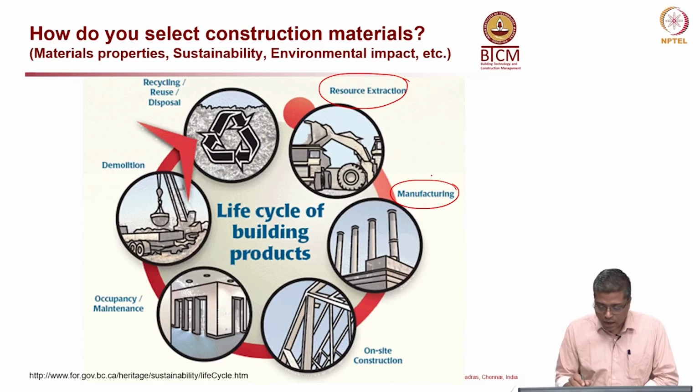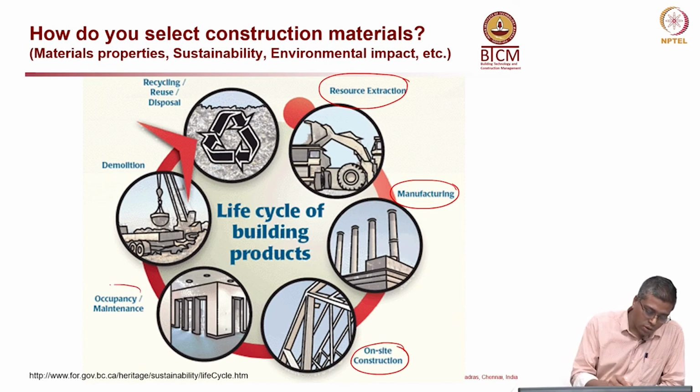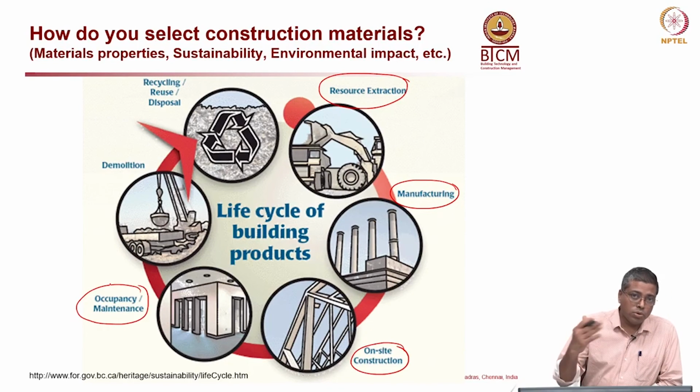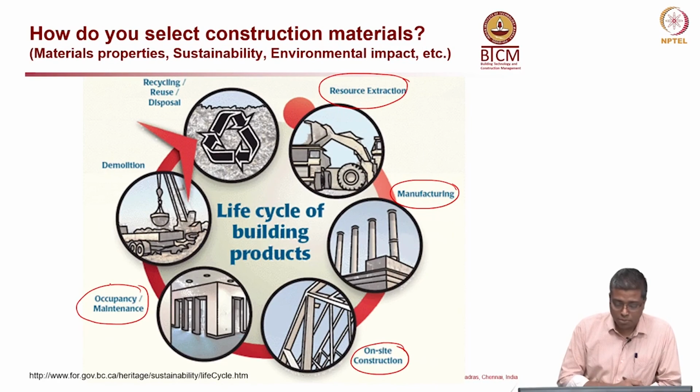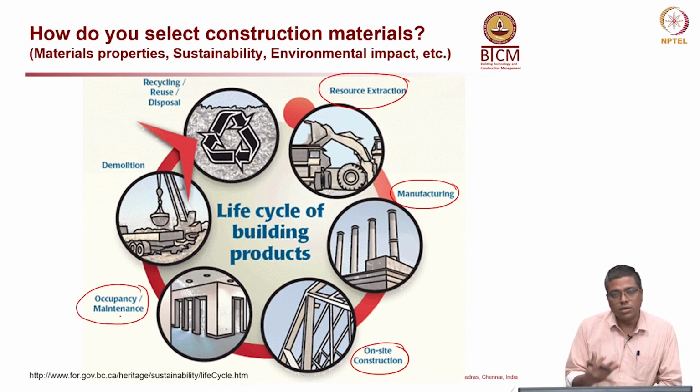You make concrete, and after that you use that material at the site. During the occupancy, the material is exposed to the external environment and also the structural loading. So, both mechanical and environmental loading are important. Because of mechanical loading, the structure might start cracking, and during the environmental loading, it might have some chemical actions on the structure, which might lead to some deterioration, which might eventually weaken the material. So, it will also crack or deteriorate.